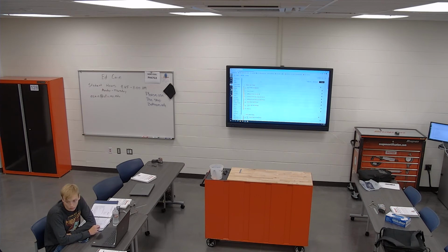And I'm like, that's gonna be an issue when I home it, because it goes X and then Z. I didn't realize, because some machines you can't move anything until you home it. Thankfully on this machine you can jog it before homing it. But it was like, how bad is that? The supervisor's like, no, it happens all the time, just restart the machine.